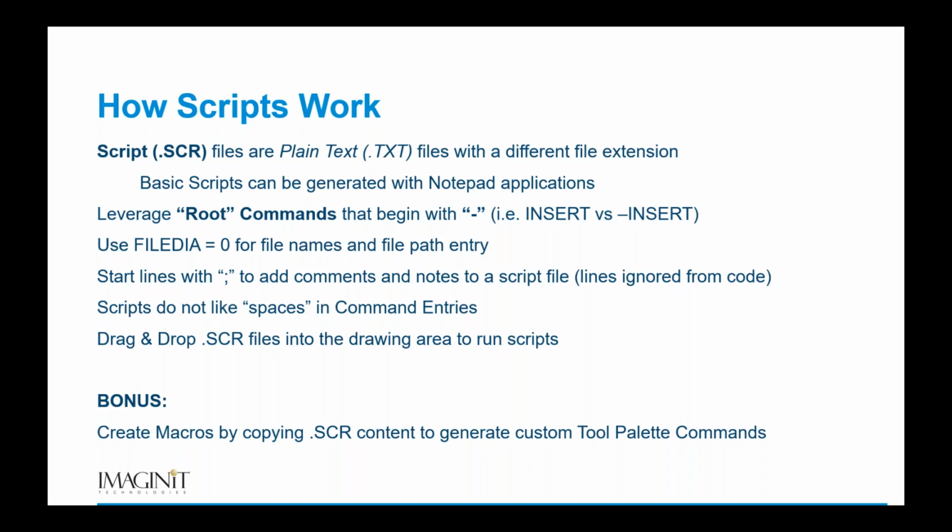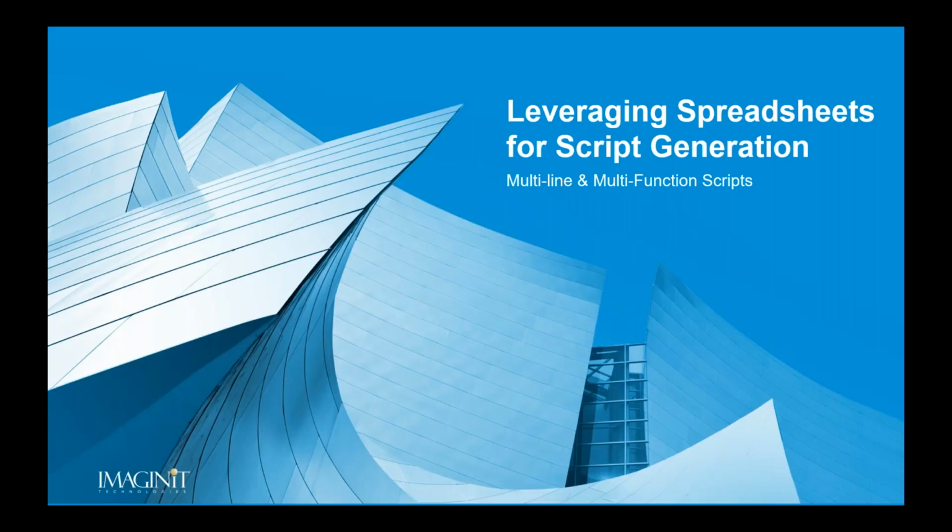And yes, the response for that, if it can't be typed using the command line, it can't be run in the script. That's generally what I go with. If it is not something that I can enter at the command line, then it's not going to work. If you're going for something that's going to be higher levels of automation, again, that's probably beyond basic script functionality. So you're looking at more like a macro or a LISP at that point. This was one of those things that we try to keep as basic as we could to start out and introduce some automation. So if you've got more advanced questions about automation, then that's likely something we need to follow up with you after the fact.